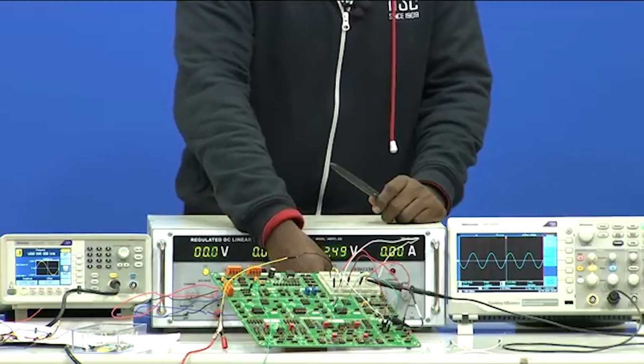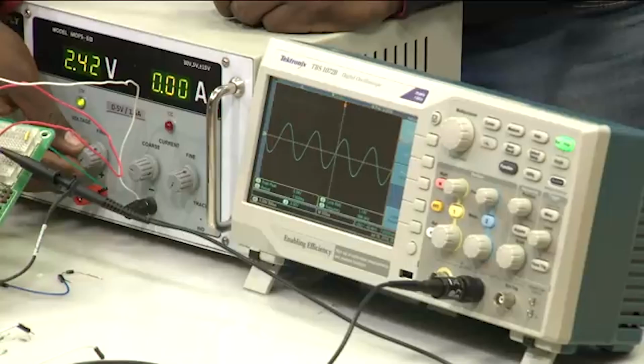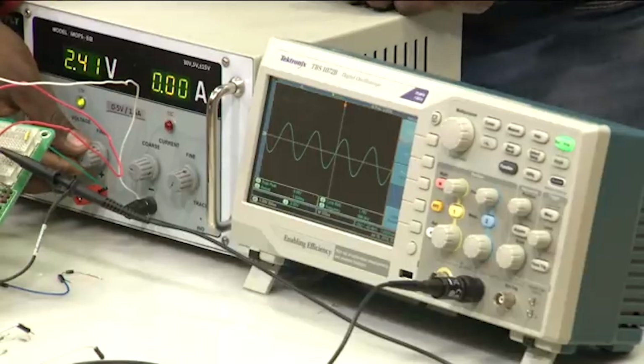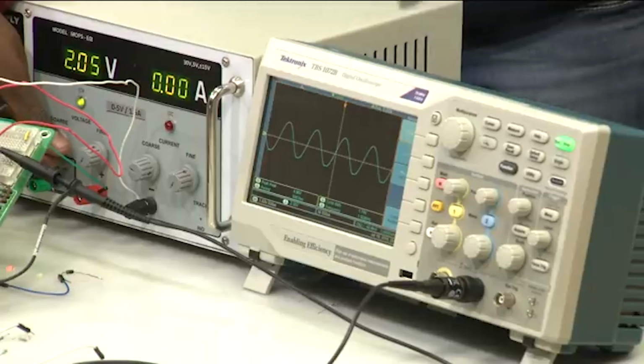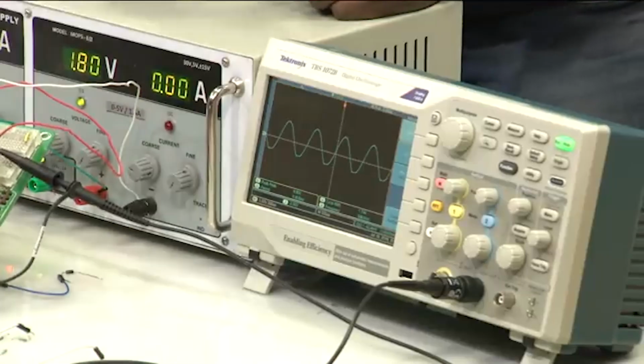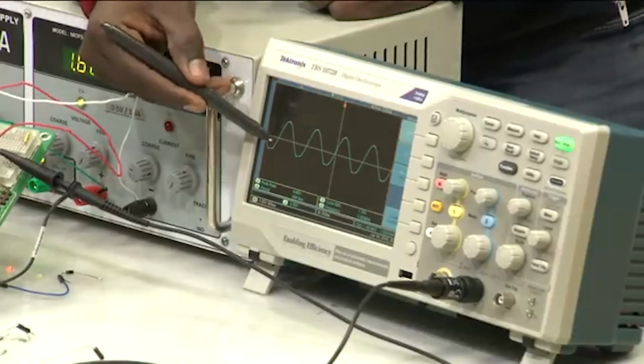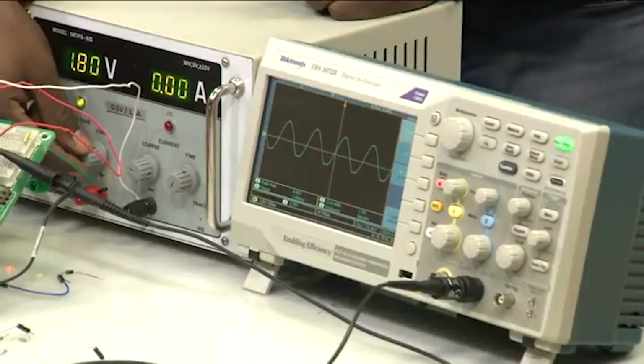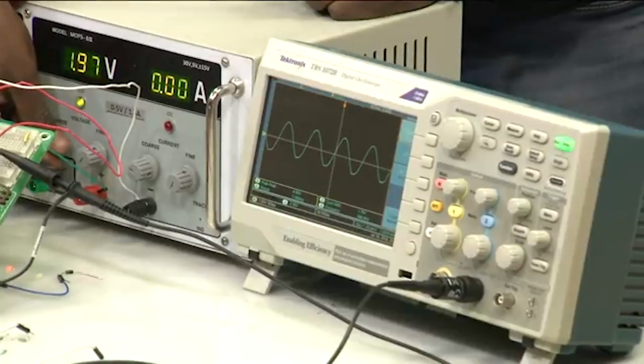Now, I will slowly decrease. In the CRO, if you see, when I slowly decrease, the signal started clamping towards the positive side. By looking at this particular point, we can clearly see that it has started clamping. The positive is 2 volts higher when compared to the negative. Now, let me decrease it. You will understand that if I increase the value, actually speaking you are decreasing it. Here you can see it was moving upwards.